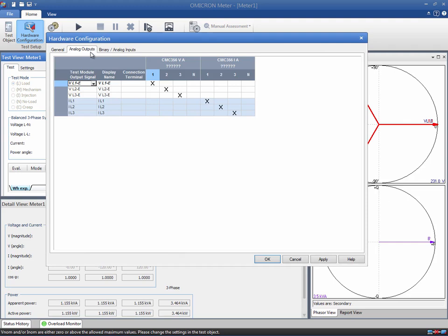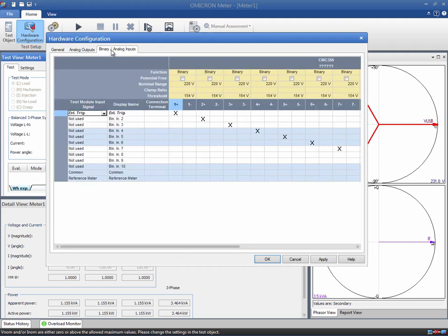This particular meter includes binary outputs in addition to LEDs. This means that there is no need to use an optical scanning head since we can route one of the relay's outputs to one of the CMC's binary inputs. Therefore, we configured the first input to be a counter and we confirmed the dialog.